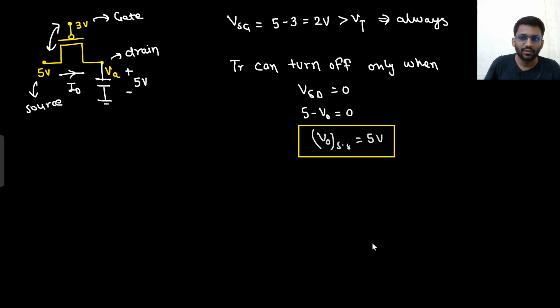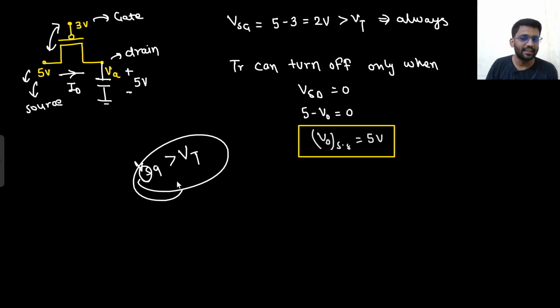Well and good. So always we should connect the PMOS at higher potential. Why is it so? PMOS can pass good one. Good one means high potential. So this thing we will learn in digital electronics. No need to worry about that. PMOS can pass good one because if source potential is high, VSG would be high. If VSG is high, that means it will be always on. If it is always on, then the complete voltage will be passed.